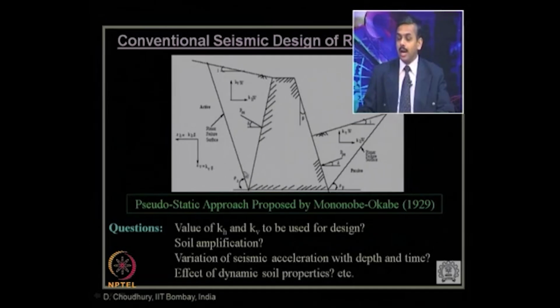To get that, either mathematically a closed form solution can be obtained by differentiating the total earth pressure component with respect to this failure angle. What method was used by Coulomb's earth pressure theory? Just a simple equilibrium method of all the forces. What are the forces?